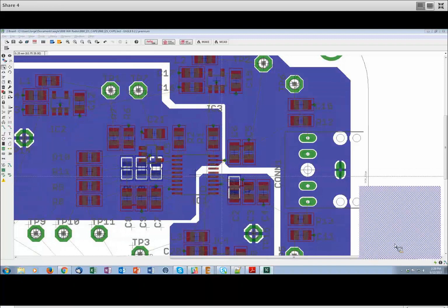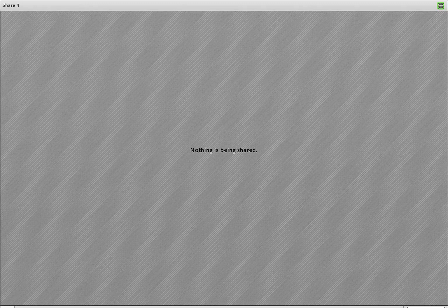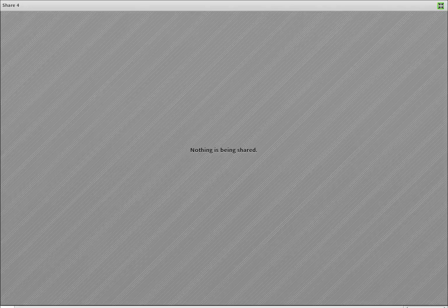That was good stuff, especially being able to route a little bit off the pad to the polygon. That's always extremely useful. That comes up quite often, where people want to use short traces to connect to a common polygon. Well, throughout this webinar, we covered the different areas of the Autorouter, how to launch it, how to get it to work with you, and the different parameters that exist that allow you to control it.